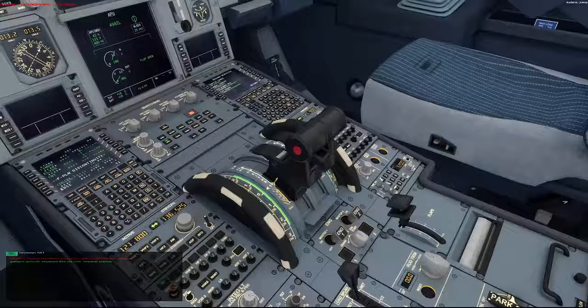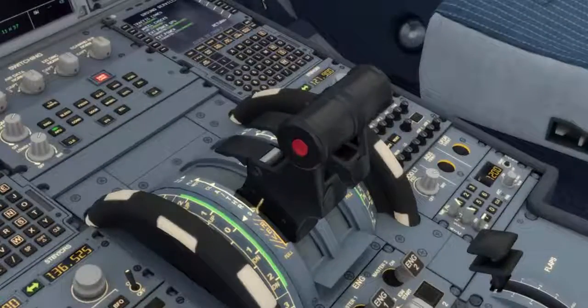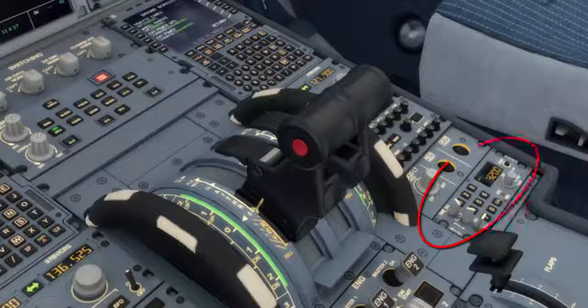And there we have one, and we'll hit the clear key and clear that discontinuity out and insert it into the flight plan. And we have also been given the number for our transponder. In this case it was 3023, so we need to feed that in. 3, 0, 2, 3.